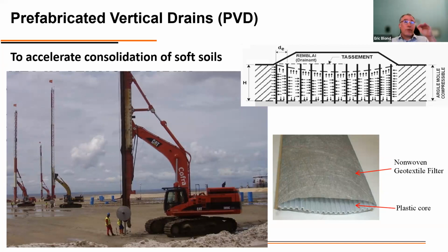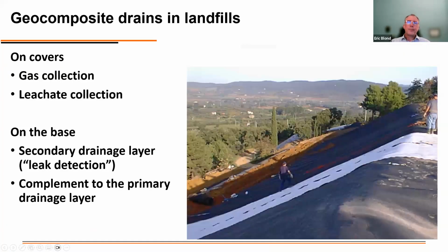when the soil has been consolidated. When it has been consolidated and it has reached the density that we are looking at, we don't want it to continue to consolidate. So in those cases, it's actually one of these applications where short service life is considered for geosynthetics.